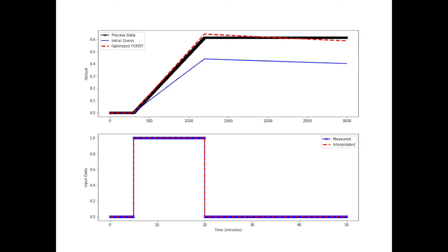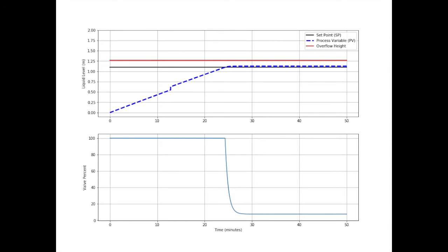We think this is because the FOPDT model is built more for systems in which it's able to adjust to a set point by adding to and taking away from a system, whereas for our system we just needed to fill to a set point without being able to decrease. In our experiment, we modeled our system using a physics-based model as discussed by Chandler. The material balance was sufficient for modeling our system accurately.